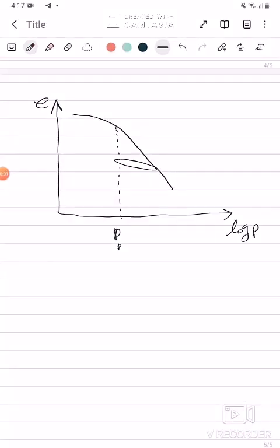Another main important difference between these two models is modeling stress path. Stress path is considered correctly in the HS or hardening soil model, but it is not considered correctly in the Mohr-Coulomb model.